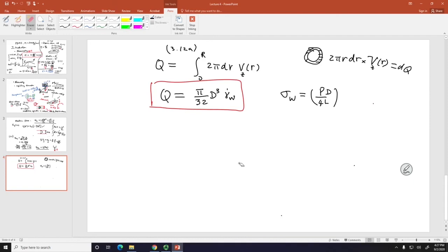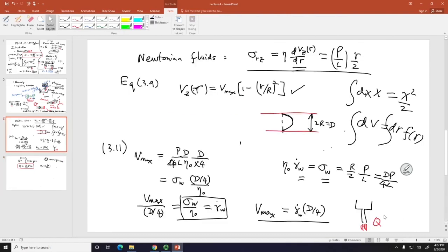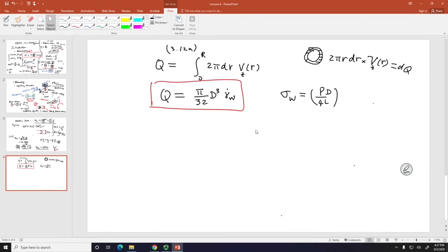But this Newtonian aspect is very useful. It gives you a sense of what to expect, how fast it comes out. At least for the Newtonian limit, it is related to, of course, right? This is nothing but viscosity, and you can, of course, plug this in. You will know exactly how Q will depend on the pressure gradient and the diameter and the viscosity of your material.